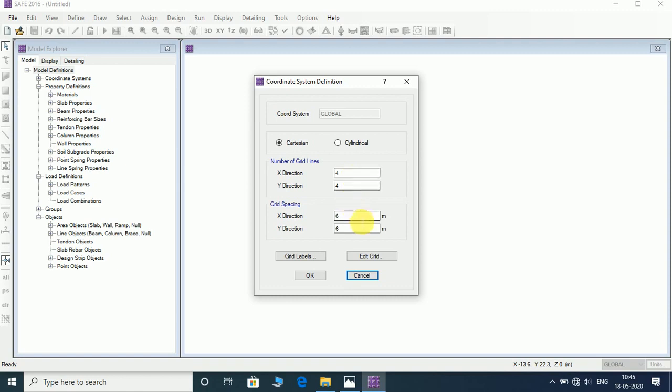Okay, it's basically a grid spacing. We can prepare a grid spacing of any distance. So along the x direction we will give a spacing of 1 meter, the same as along the y direction, and the number of grid lines along the x direction comes out to be 19, because it starts with 0. So it's a span of 18 meters. When it starts with 0, we consider that, so we need to give one extra, that is we get 19 there.